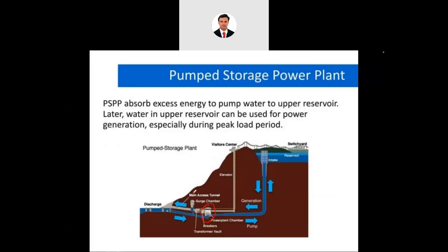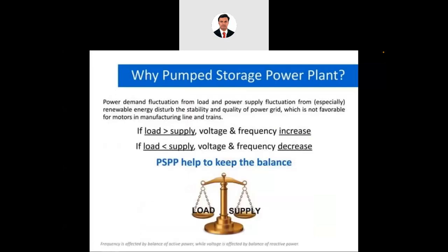When there is excess requirement, when demand increases during the evening, we use this water to produce the excess energy. During that condition, this device works as a turbine. That's how pumped storage works.